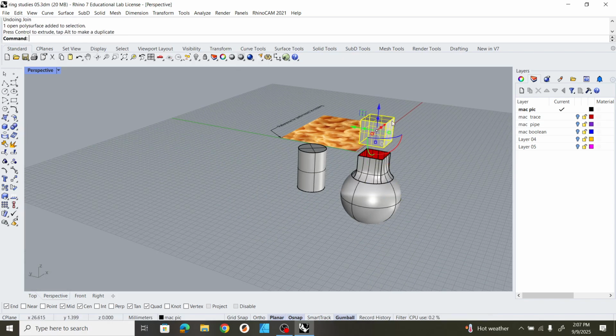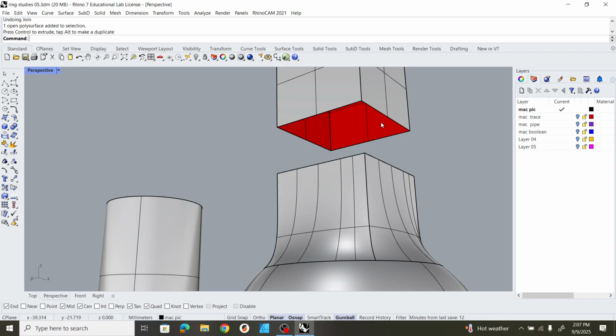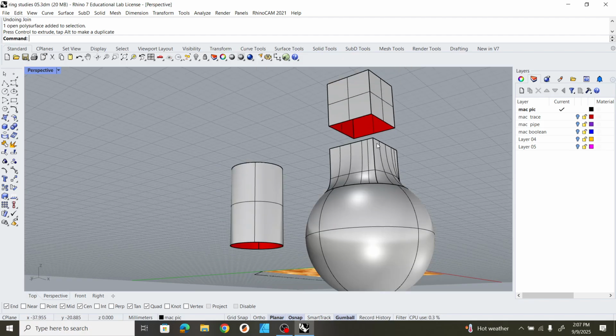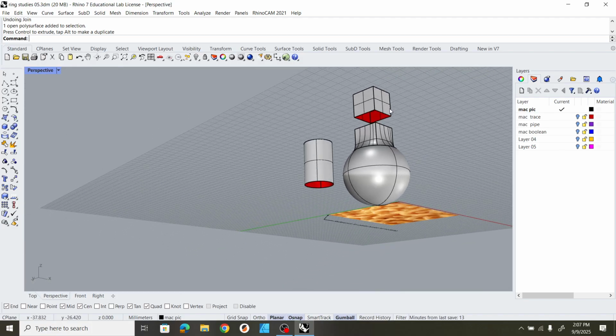As they are, I've changed something. In the handout, it tells you how to do this, but you can change your back face color. Surfaces have a front face and a back face. That is generally when you get in trouble, when the back face starts to intersect with the front face and they intertwine. So you can change the color of your back face so you can easily tell when that's happening, because that will mess your objects up most of the time if you're trying to print stuff.